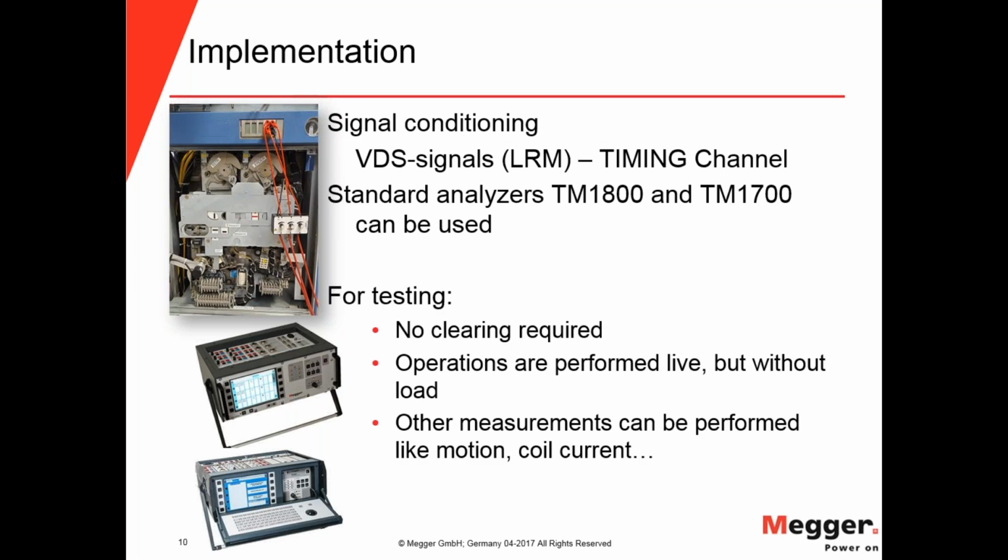For testing, the advantage here is that you don't need any grounding. The operations are actually performed in live conditions. However, you should disconnect the load from your cable to prevent arcing and so on while switching.